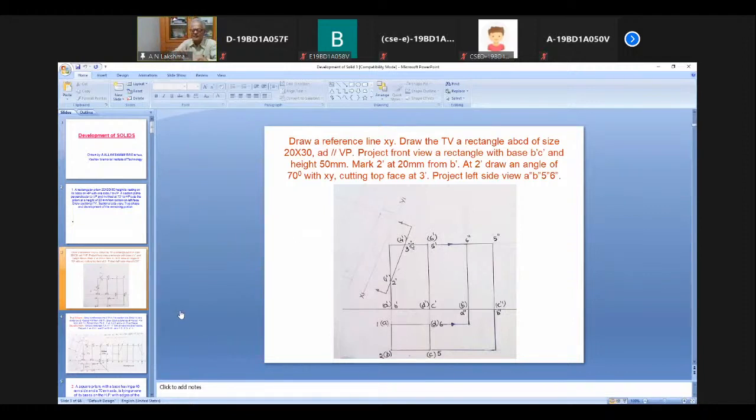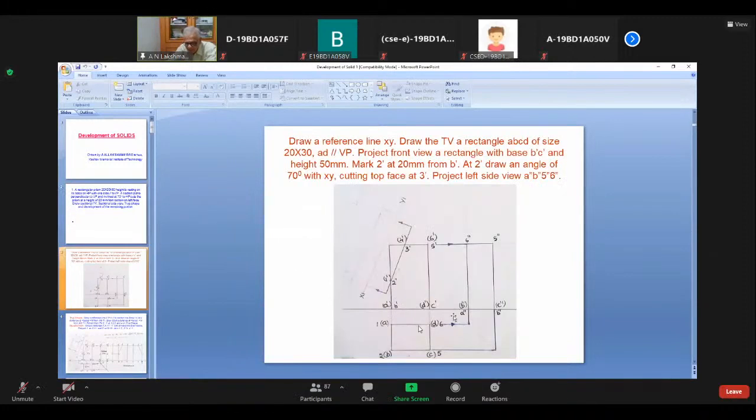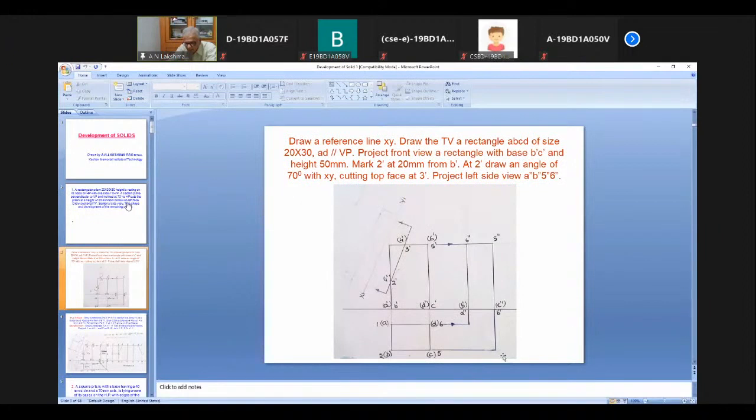What I put as 3, 4 here is cutting in between, so these things will become 5 and 6. Now, I draw a perpendicular from here. How do you draw the side view? For the side view, you project from here. You draw any line up to this. From here, you are not able to see that. There is a line here, which is at 45 degrees.